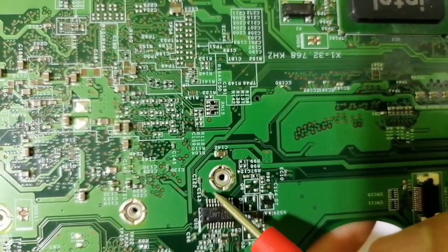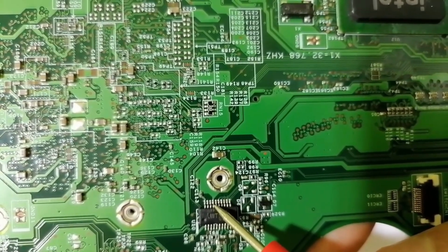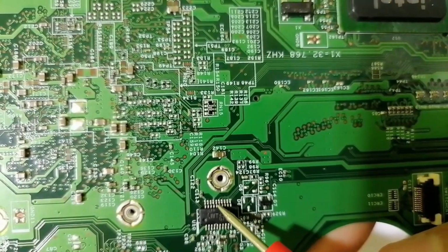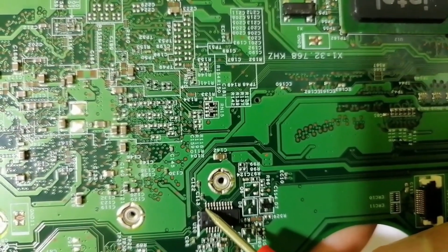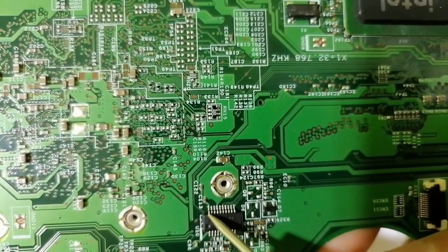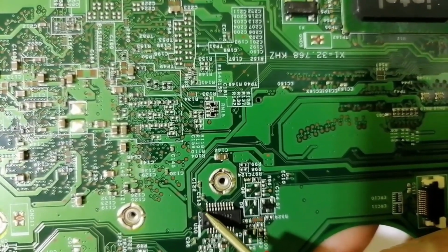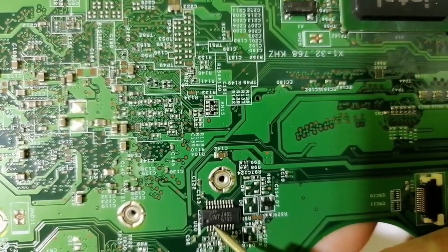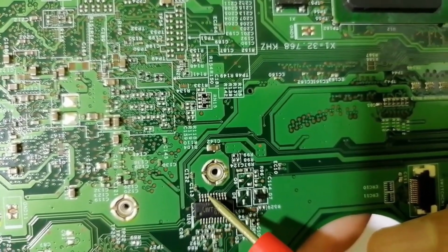So this pin is for ground, this pin is for power, and those are just control signals. As you can see, the power pin is connected to a ceramic capacitor in order to be filtered. So always the power pin is connected to a ceramic capacitor. Do you see, guys? I can know about all pins without the schematic.